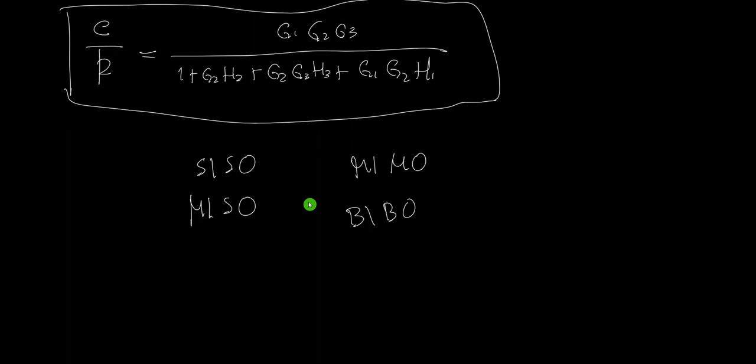So what is the superposition theorem? You remove all the sources. In circuits, we call them sources. But in block diagrams, we just remove all the inputs and retain one. Remove them all except one. Then solve for the output C. I call that C1.